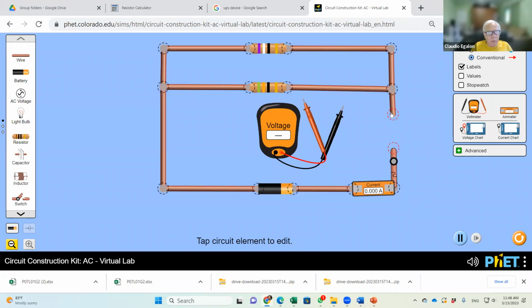Why is that? Because the resistance between those 2 points is equal to infinity, the resistance of air, okay? Or the resistance of vacuum. You have air between those 2 points, so you have a very large resistance between those 2 points. And same thing that you get here. You have a very large resistance between those 2 points. That's why you're getting a measurement of 0.